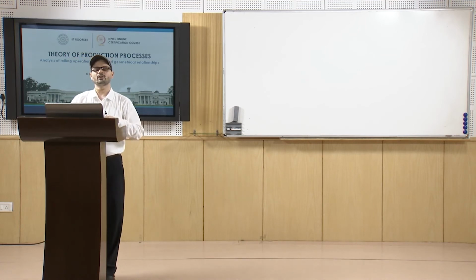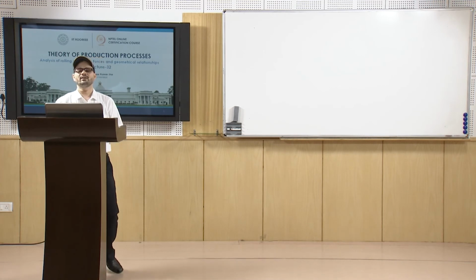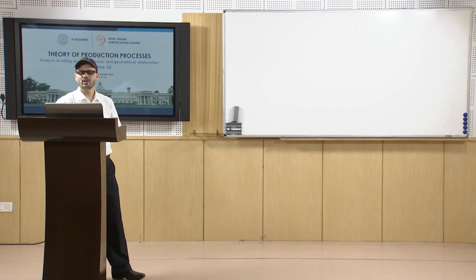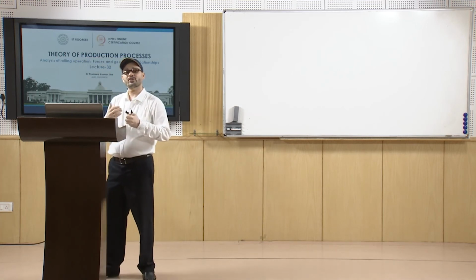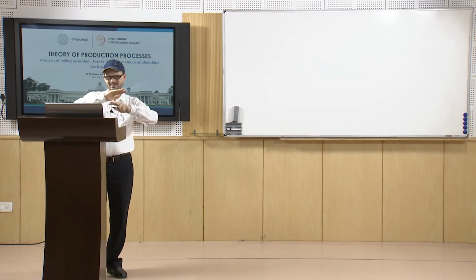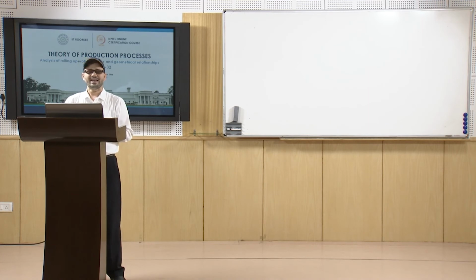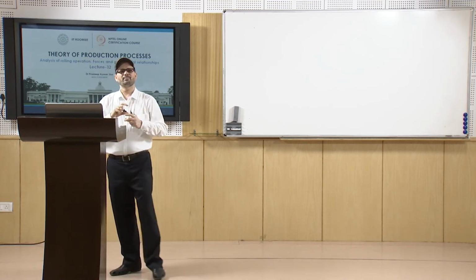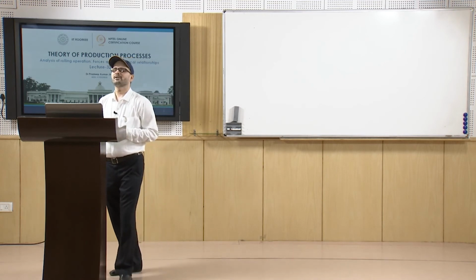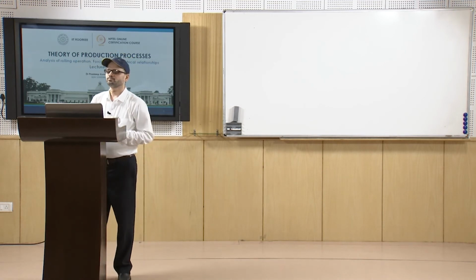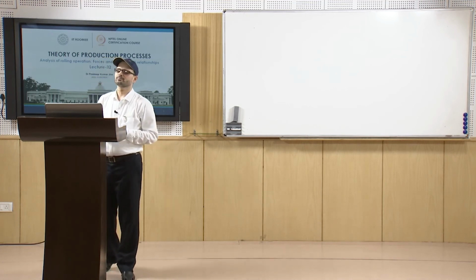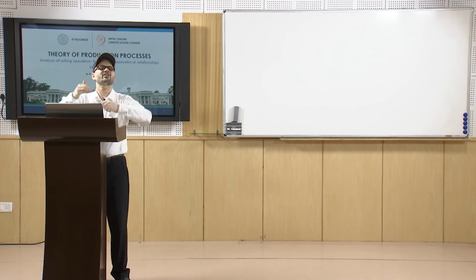So, what are the main parameters in rolling? Basically roll diameter, then deformation resistance of the material, which is influenced by metallurgy, temperature and also strain rates. Friction between the roll and the strip surface is also an important parameter. As we have seen, rolling load will be the roll pressure multiplied by the area of contact. If we neglect the friction, then the pressure becomes the yield stress of the material.